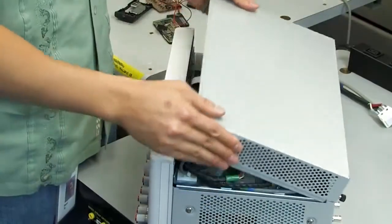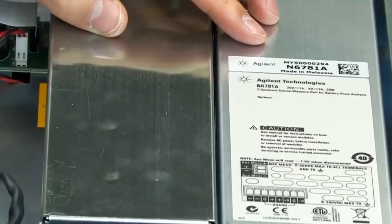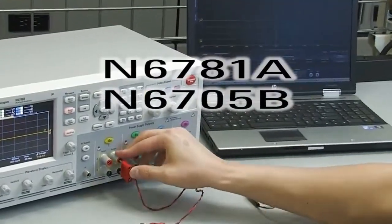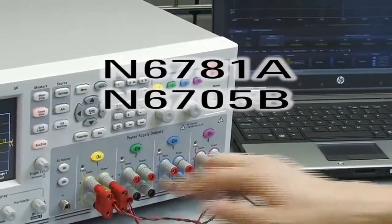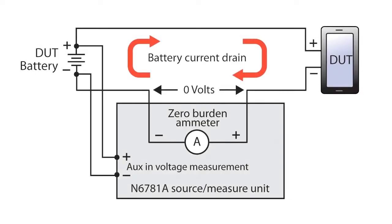We conducted a battery rundown test on a GPRS smartphone using an Agilent N6781A 2-quadrant source measure unit to log the battery rundown voltage and current. The N6781A and the N6705B mainframe have a number of unique features and advantages that provide improved accuracy and greater insights, specifically when you conduct a battery rundown test. It offers an independent DVM input for logging the battery voltage, and it is a true zero-burden shunt, eliminating the voltage drop problem of conventional shunts.